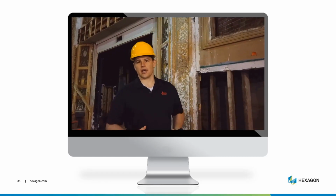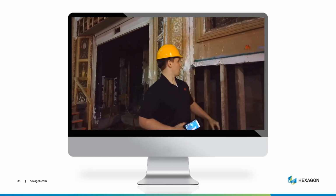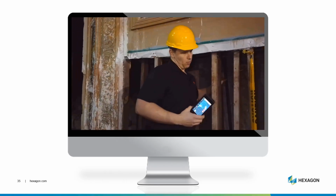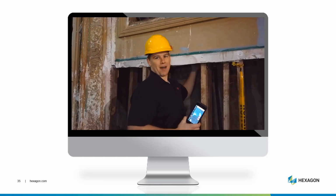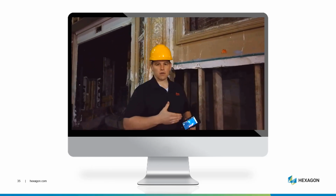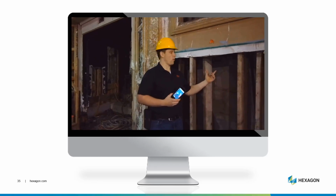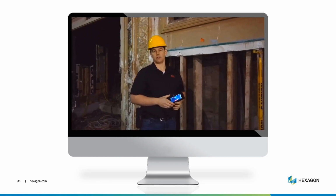With tripod-mounted laser scanners, it's all line of sight. So our point cloud will show the plaster, the studs, and even this pipe here, but what it will not identify is the L shape behind the plaster. So with the BLK 3D, we can add a measurable image as a geotag in the point cloud that can be referenced later in our LGS file.